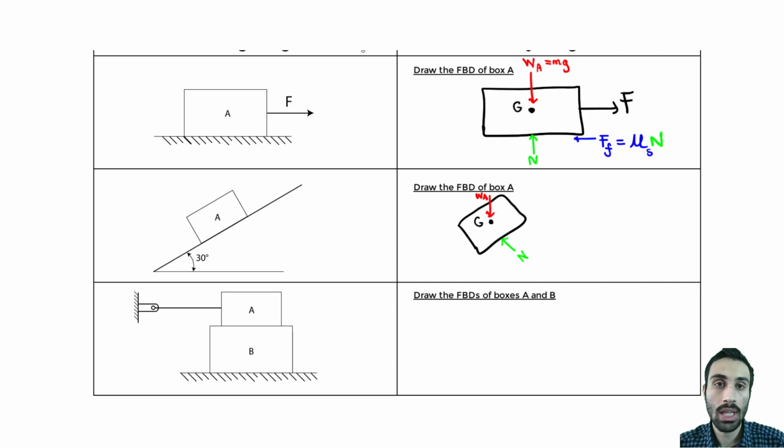So what I'm going to do is say you have some frictional resistance acting this way. Friction force, which is mu static times the normal force, same idea. And I drew that in that direction because friction is like a resistance force, and it resists the direction of impending motion. So think of it as the direction of motion, but when we say impending motion, is it about to slide down? Is it about to impend and slide down, or is it about to go up?